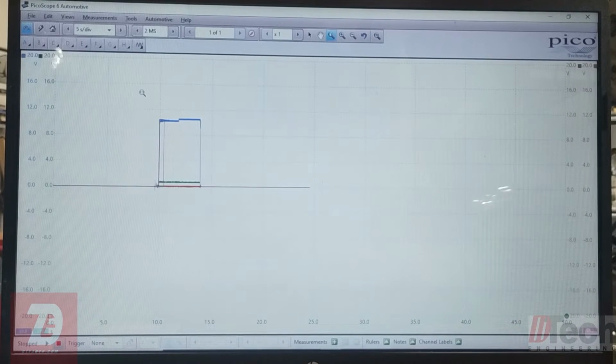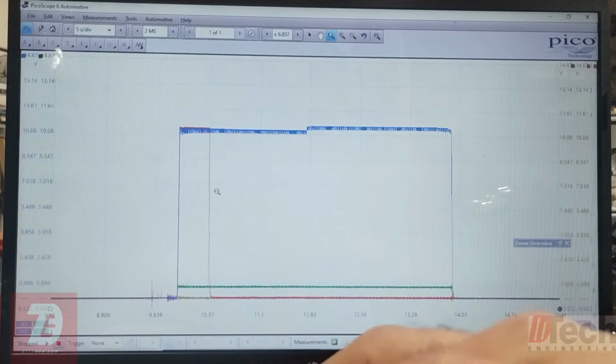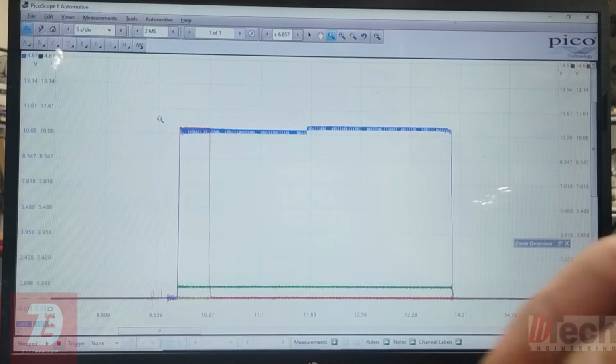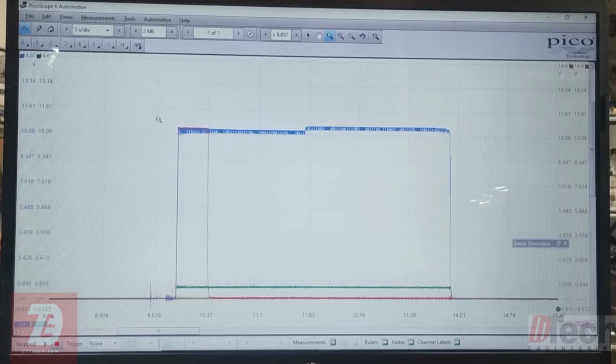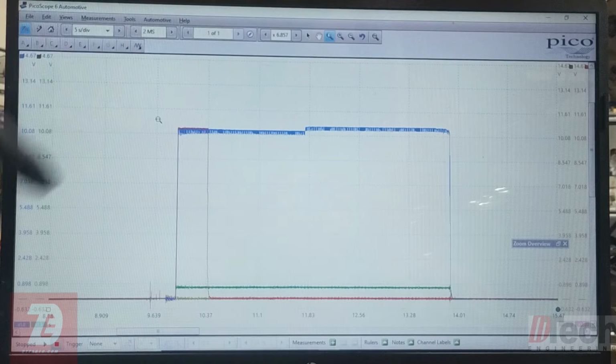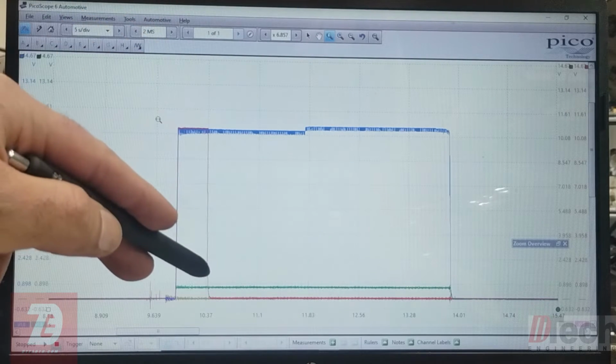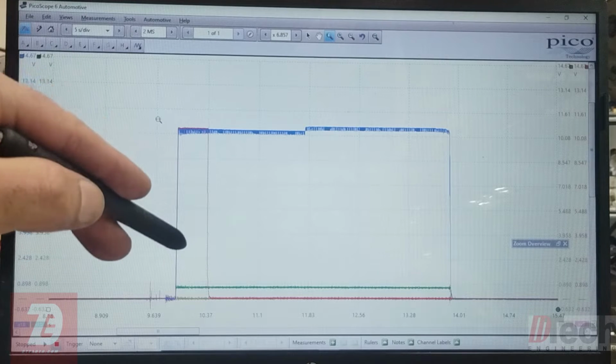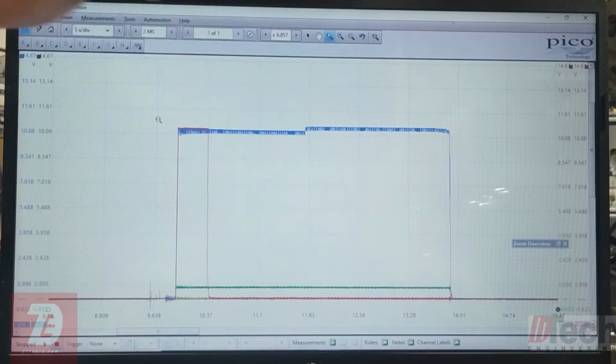Alright, let's take a quick look, but we already can tell that we don't have that pinging on the left side with that sensor from the right, and voltage stays up constant, doesn't drop out like this side because there's no sensor there. Circuit is intact, and so voltage stays constant. So it's not the sensor.